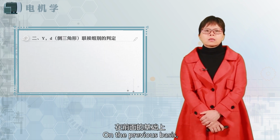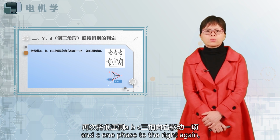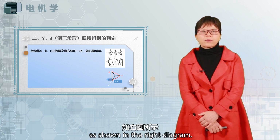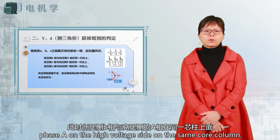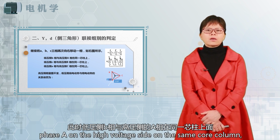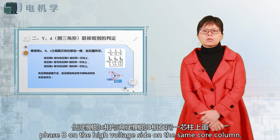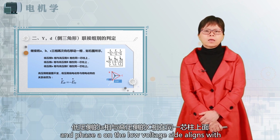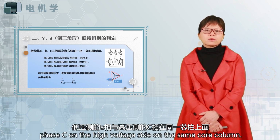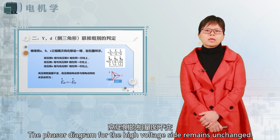On the previous basis, move the low voltage windings A, B, and C one phase to the right again, as shown in the right diagram. At this point, phase B on the low voltage side aligns with phase A on the high voltage side on the same core column. Phase C on the low voltage side aligns with phase B on the high voltage side on the same core column, and phase A on the low voltage side aligns with phase C on the high voltage side on the same core column. The phasor diagram for the high voltage side remains unchanged.